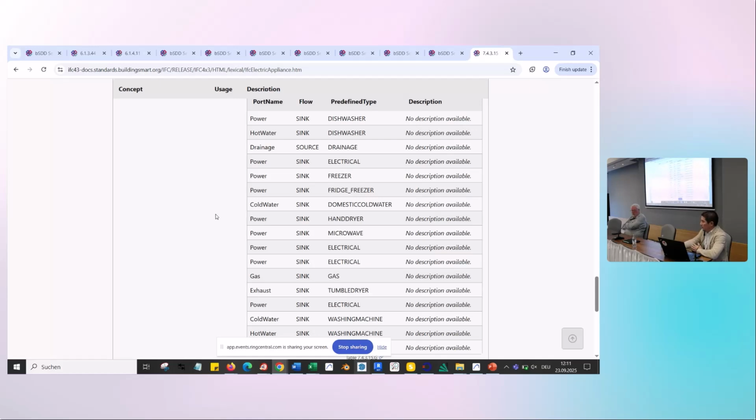And as you can see, if someone creates a bSDD, please be careful, deep dive. You have to find someone who will be helping you and check, especially manufacturers, if you're dealing with creating a dictionary, or some association dealing with a dictionary for a specific area. Let's say in our case, we had this heat pump area, where building energy retrofitting is really important. Then we can use that class, and we will go to bSDD, search heat pump. Okay, we need to map our model with IFC unitary equipment, not with energy device, but we have more chances. And the same way with photovoltaics, like PV panels, solar devices.